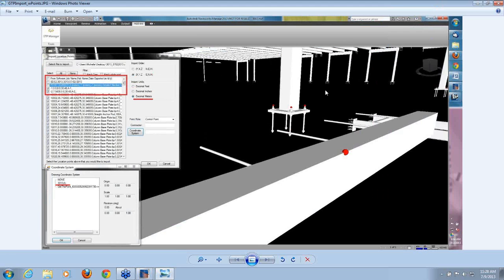this is a screenshot from Navisworks. So it imports with a Get The Point manager. It's a plugin in Navisworks and Revit, and what it does is import these little red points here into a model. Now this is another IFC model that was exported out of an SDS2 job as well. You can look at these points and where they're located in the model, and if someone has field scanned an actual location, you could compare these 2 points to see how far off they are. If they need to be adjusted in your model, you can get that information and adjust it so everything's built correctly. So that's just a little something coming down the line.